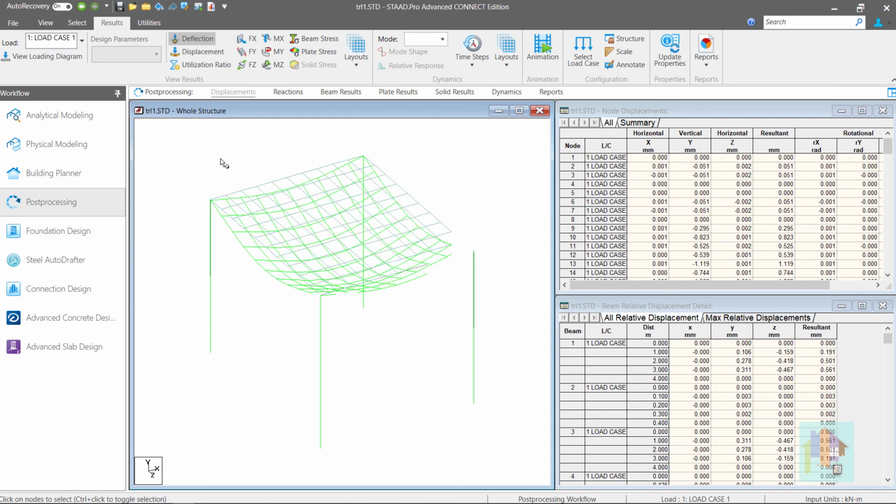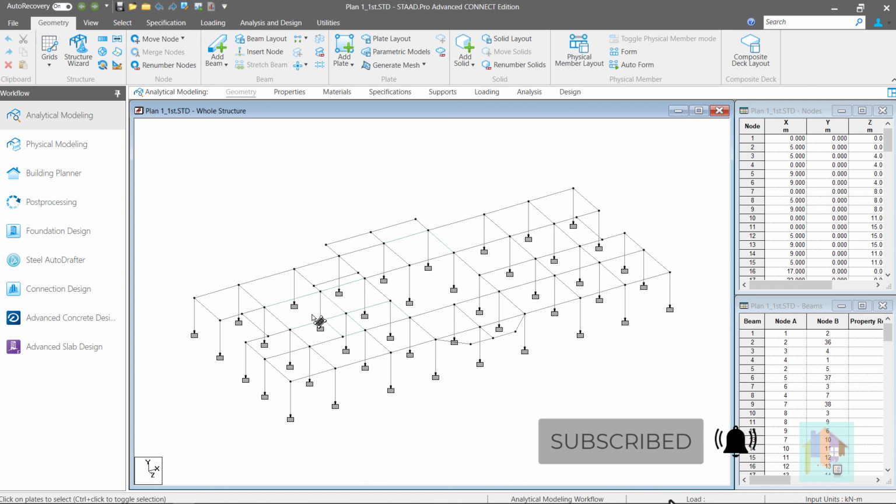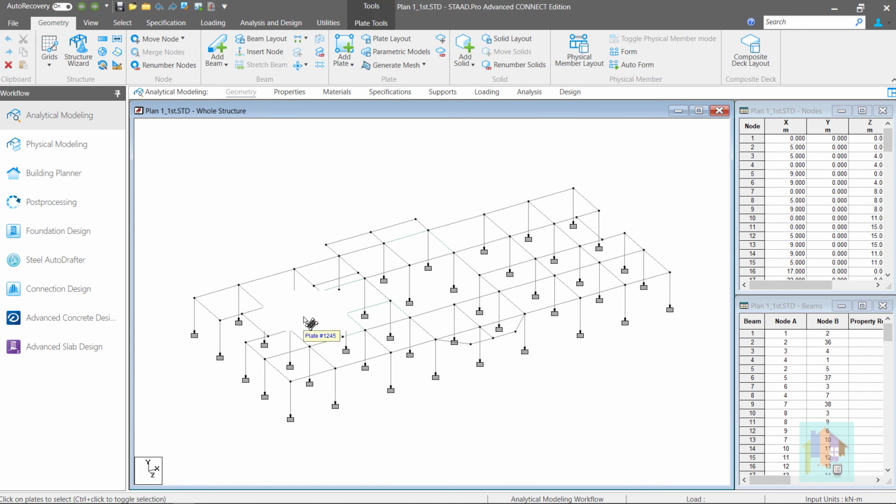There is another major reason from finite element analysis point of view. With fine mesh, accuracy of the plate results increase. I will discuss this in future. Anyway, from these examples, you can easily understand why we should avoid modeling the slab using a single plate. This model with isolated plate is structurally erroneous and incorrect.